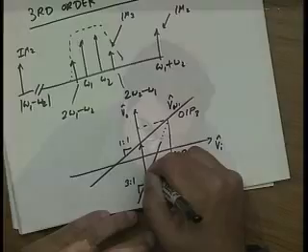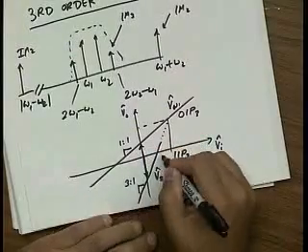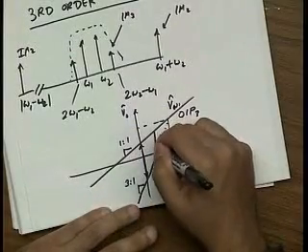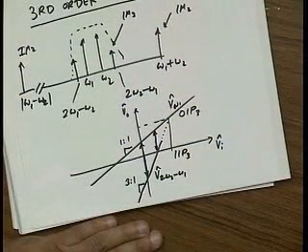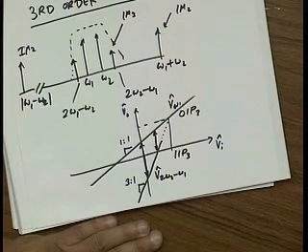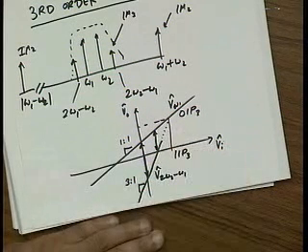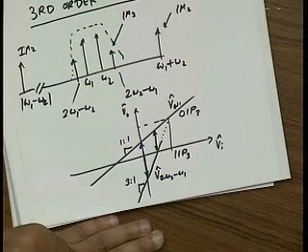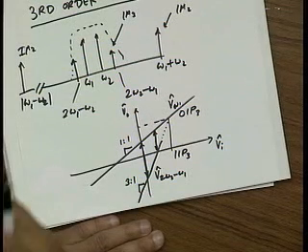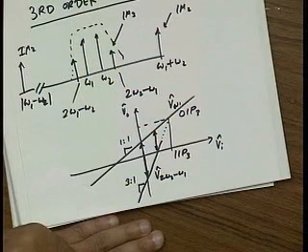Anybody? So if this is the IM3 at a given input power, if I move over 10 dB, how much does the IM3 decrease? By twice, right? So 20 dB. So if I want 100 dB IM3, I have to back off 50 dB from the IP3 point. So operating at minus 50 dBm would give me 100 dB theoretically of IM3. Okay?